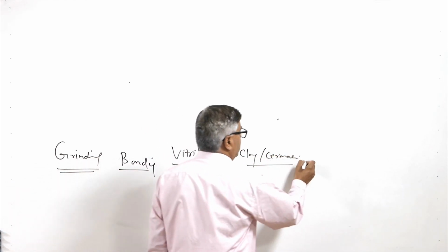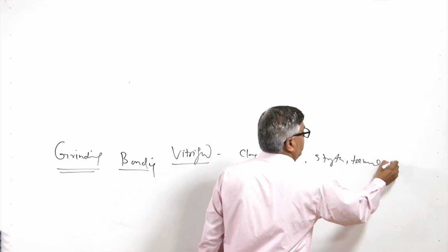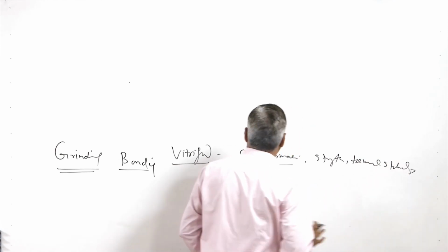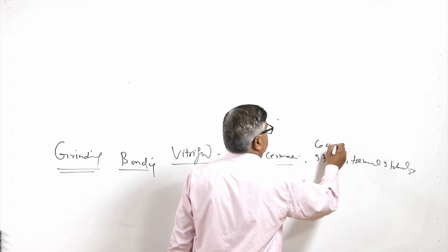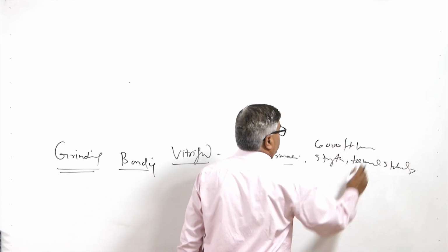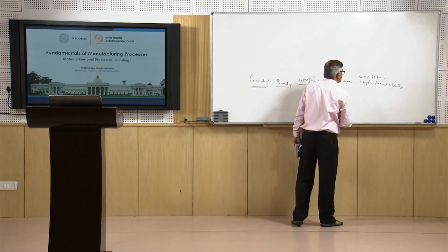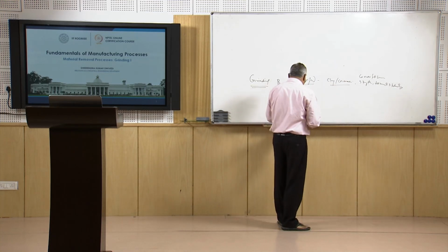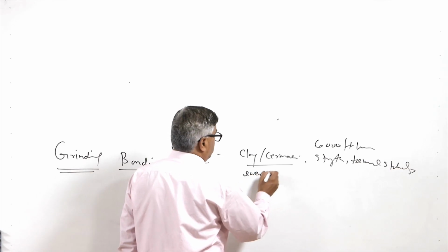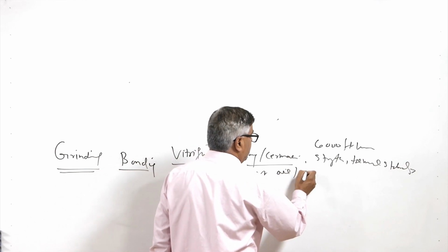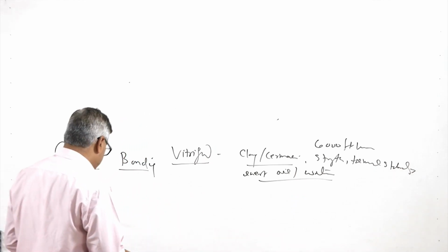It is very good in terms of strength and offers good thermal stability, and that is why it is used for most common purposes and can run effectively up to 6,000 feet per minute, or 2000 meters per minute, without much difficulty. It also shows inertness to oil and water, so it is equally good for wet conditions.